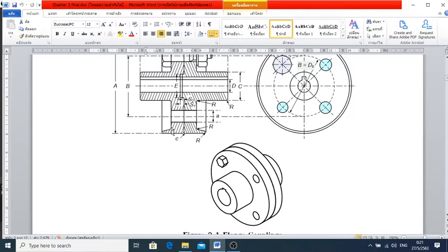This one is made of cast iron, so of course it's going to be a brittle metal. It's available, so you can go buy the cast iron one. Another way around, you can make it by yourself, because this is going to be easy. For instance, you cut the flange itself with a gas welding cutting machine, cut it in a round shape, and grind it.